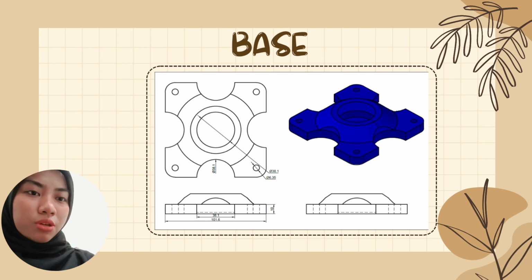Finally, we draw a square shape with a length of 12.7 millimeter in each corner of the shape for the screw hole. We also draw a circle with a diameter of 6.35 millimeter from the corner of the small square that lands on the surface shape. We repeat the previous step for each corner. Then, to make a hole, we press pull by 10 millimeter. So that's all the steps to draw the base. I will pass to another person.